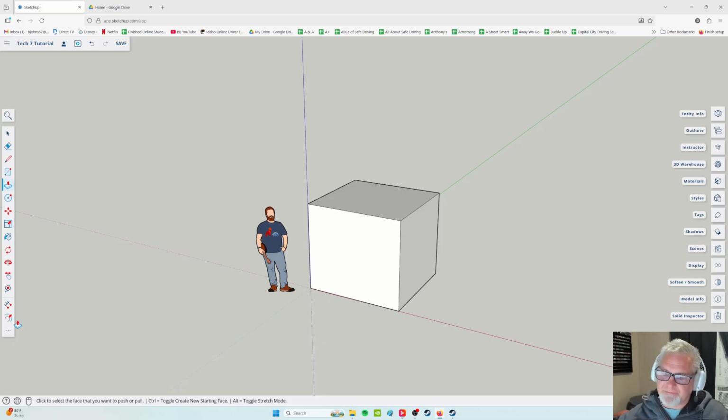But that's a dimension line. If you roll your mouse over it, it says dimension. So I'm going to click on it once, and I'm going to click on a corner, and then the opposite corner. I'm going to click when it turns into a dot. And then I'm going to drag it out to the side and click. I can choose where to place those.